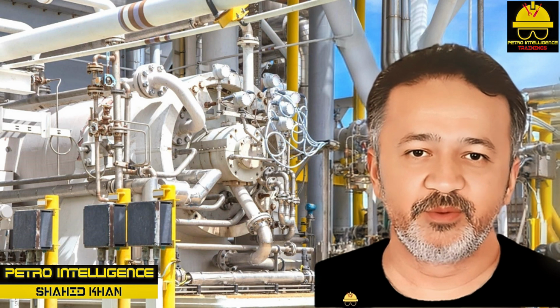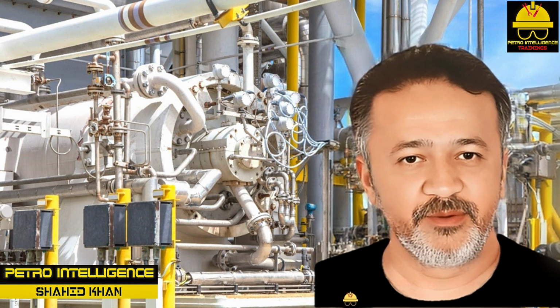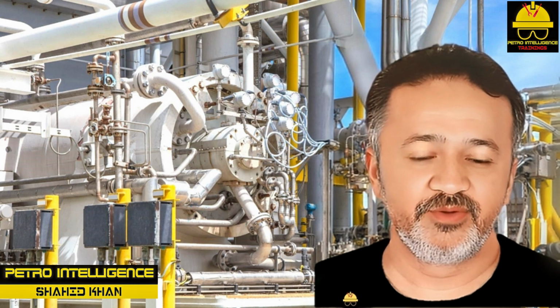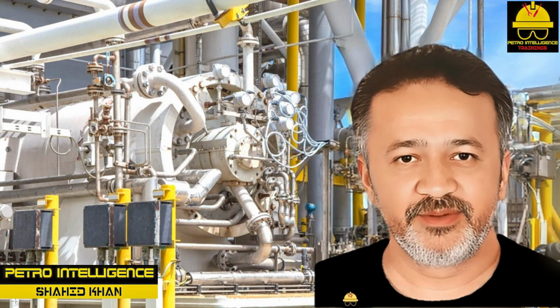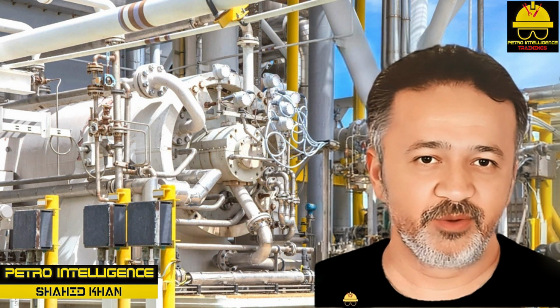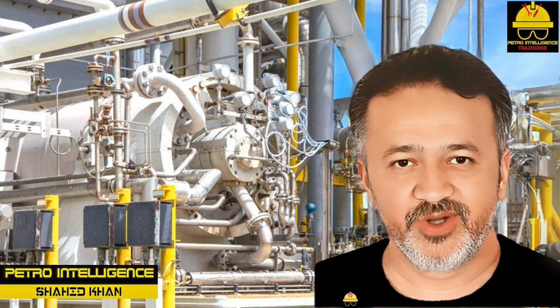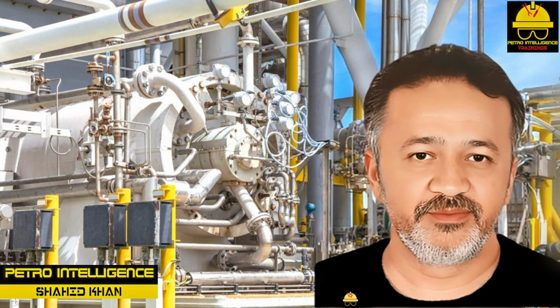Positive displacement compressors remove a set volume of gas for every rotation or stroke of the primary transfer elements. In process systems where fluid density and suction pressures vary, positive displacement devices provide steady service. Rotary compressors can deliver pressures between 100 and 130 psia. Reciprocating compressors discharge pressures that range from 0 to 30,000 psig.